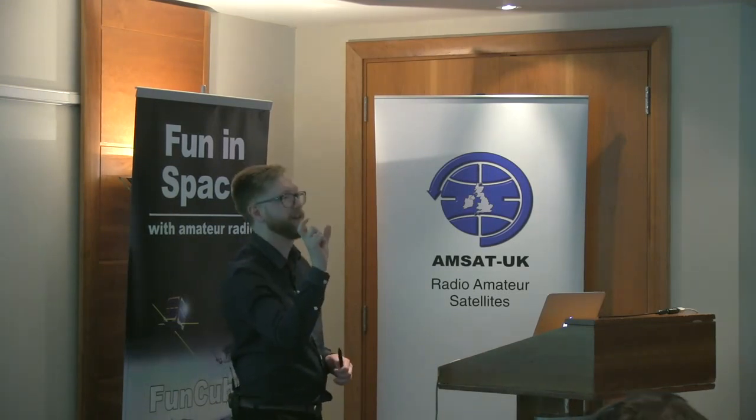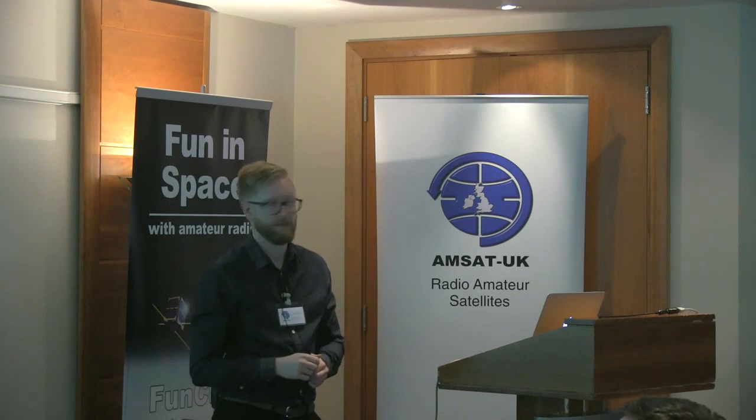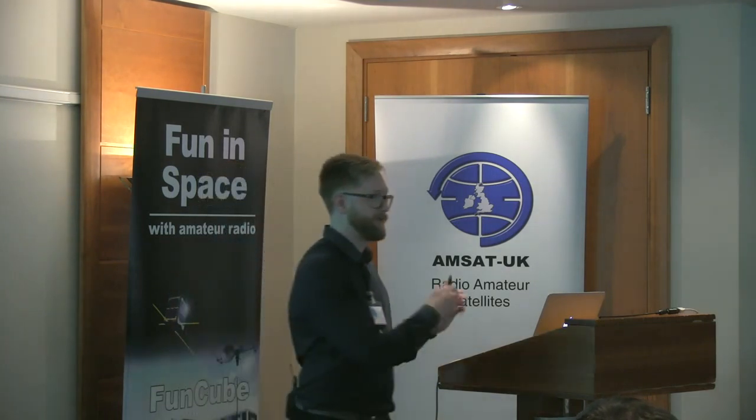If you need to, I can perhaps help out by giving you some WAV files where I go, okay, in that little WAV file there, there's definitely a BPSK 1K2. In that file there, there's definitely something else, FSK 9600. There's ones in here that I've got for Firebird, which is a 19K2 one. And there's excellent repositories online for LilacSat, which is, again, BPSK. But the ones that I'm interested in and looking at now are things like HORU4, so QPSK signals. Let's just keep broadening it out and getting decent reference signals into your system.